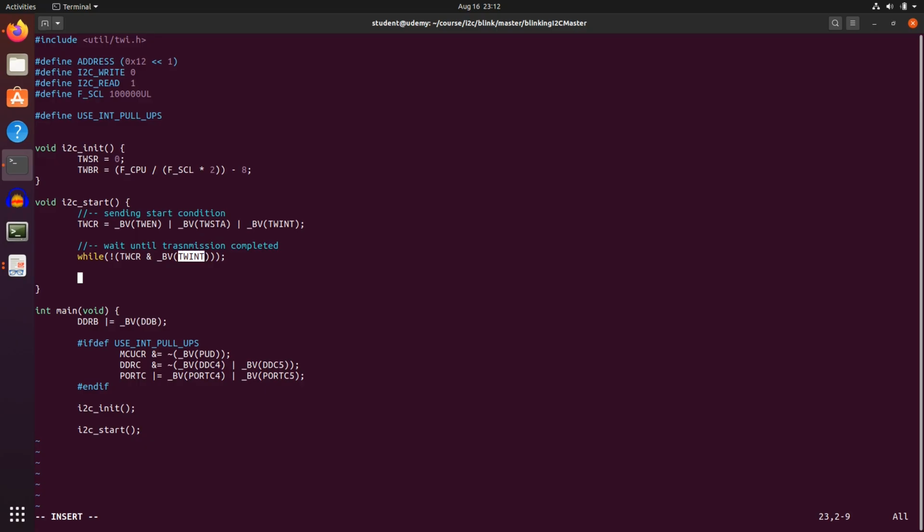If it is set, then I can proceed with the slave address. However, first I have to check the status register if the start condition has been sent successfully.